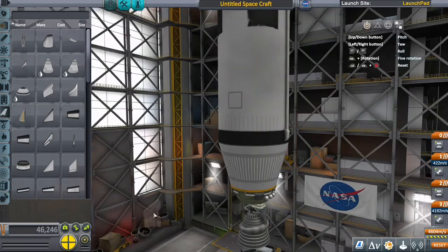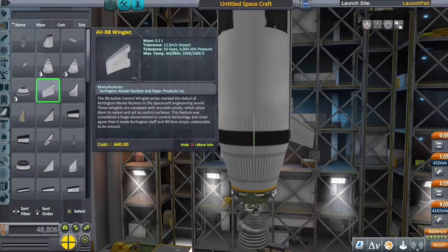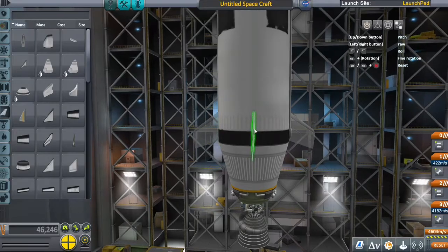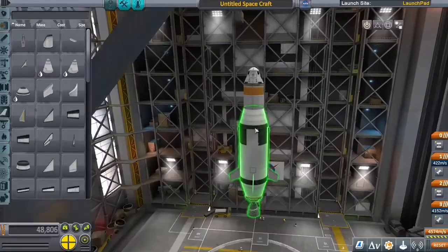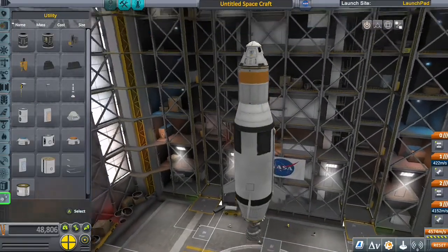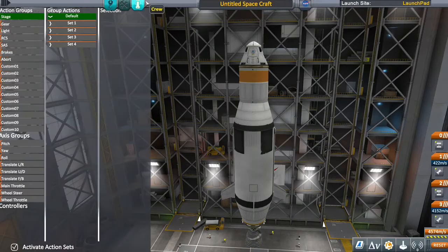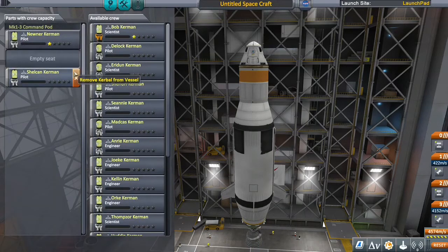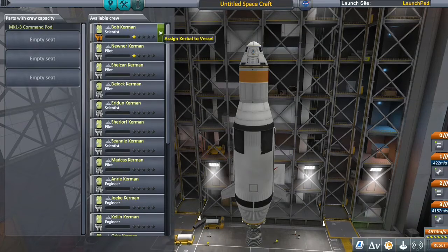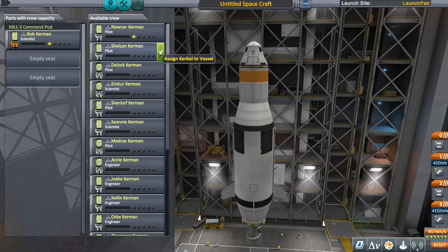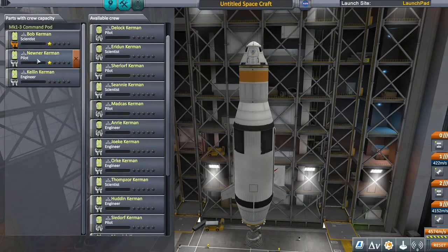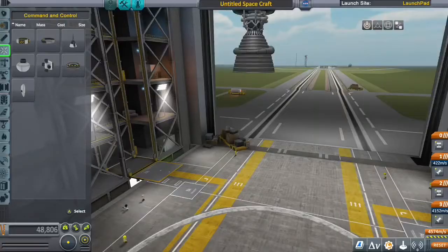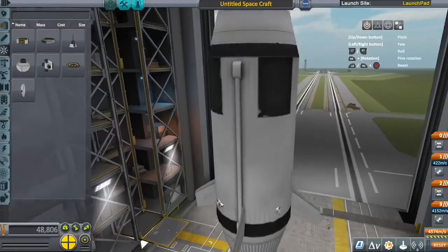But make sure when you're building rockets like this, you add RCS thrusters, just because, once again, it makes it a lot easier to dock due to the fact that you can maneuver more accurately in space. If you did not add RCS thrusters, you'd have to burn retrograde to your target to slow down and then turn all the way back around and burn towards it once again. But you'll see very soon how helpful RCS thrusters truly are.